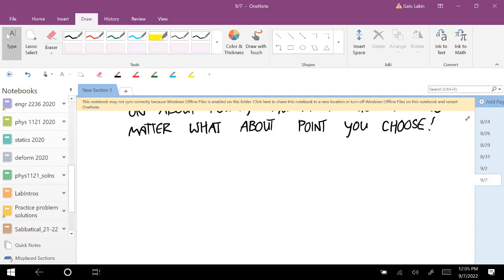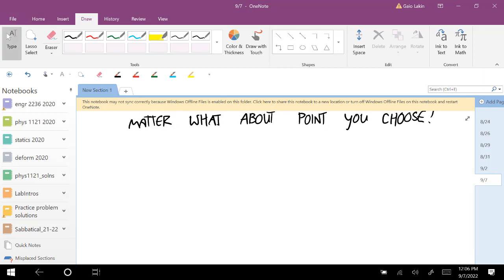So I'm going to just go through a little proof so you can see how this works. It's really surprising. But what this is going to mean is that when you see couples on a free body diagram, they're not going to tend to be drawn as equal and opposite forces. They're just going to tend to be drawn as a pure moment, because you can choose any about point and it's still the same moment.